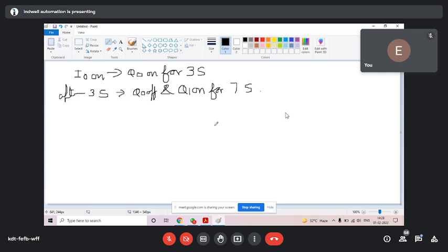No, the question is in general. See, let us say for an example, my input to the timer is from a switch, and the signal is that after 3 seconds, the timer should be on. I'm holding the switch for 5 seconds and then releasing the switch. So when I release the switch, the output goes off. Is that okay? Yes. See, if you don't have a latch, then it will be off, obviously.